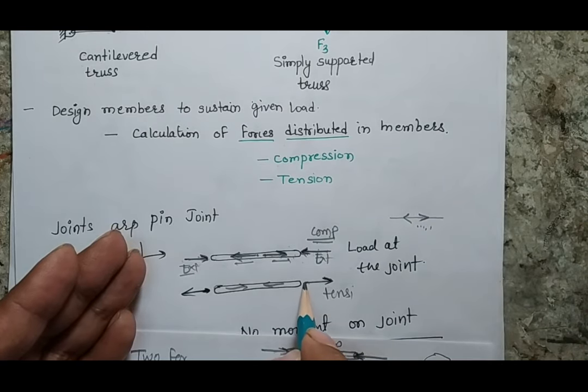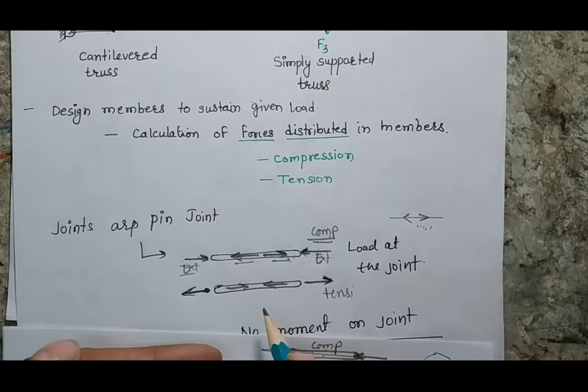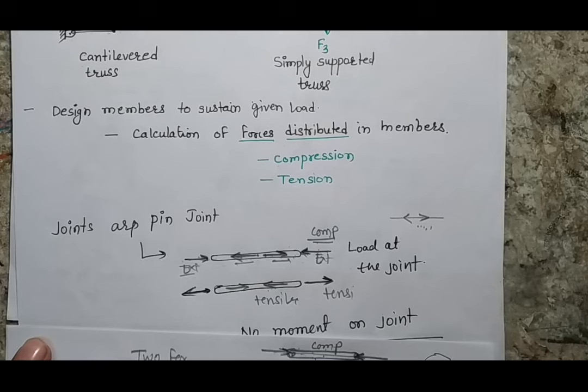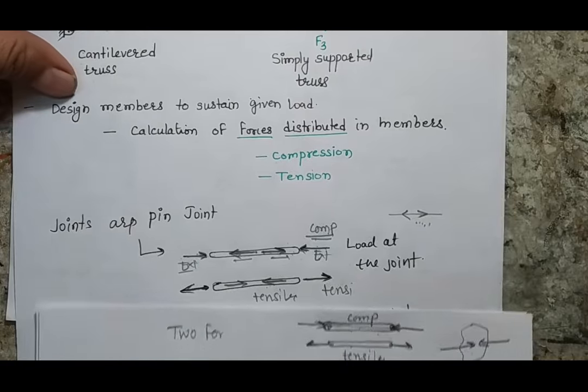On the other hand, if the external forces are acting in this way, the internal force will be generated going inside, and the nature of the force will be tensile here. So we should keep it in mind, and I will repeat it again, how we represent the forces in the truss member, basically the internal forces in the truss member.